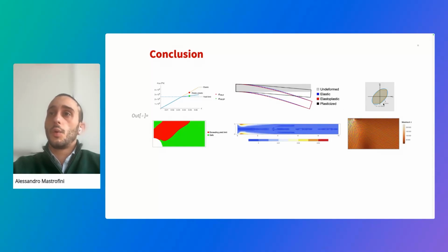plasticization effect. We can have different hardening criteria from the one related to metals directly into the soil. We can evaluate the final plastic strain, and we can also use all this information to evaluate if the material is safe or not by failure criteria based on the elastoplastic criteria. So if the material is still in elasticity, it can recover all the deformation without any danger.